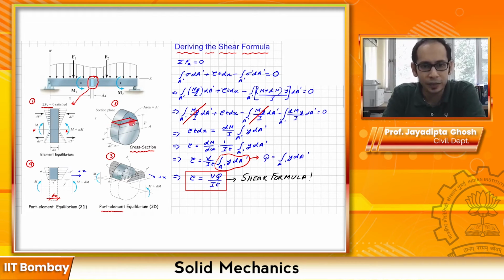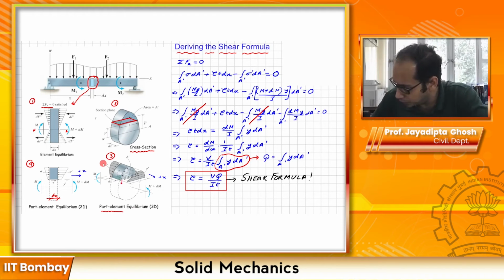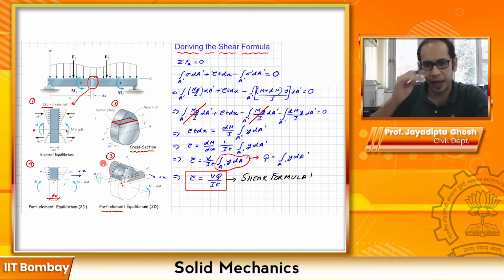t is the thickness of the beam. It's a prismatic beam and may not be rectangular, it may be this shaped or some other shape. So t is wherever you're calculating the tau. See here, this tau, remember we're calculating here. And why are we calculating the tau here? Because at that particular point, this tau is actually the tau which is going to happen over here because of complementary shear, remember? So this tau that you see over here is going to be equal to, and I'm just going to draw it with a small line, this tau that you will have at that particular interface because of complementary shear. We'll come to that in a minute, right? So I and then we have the t, which is the thickness of this one over here.